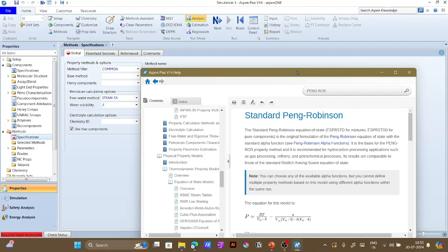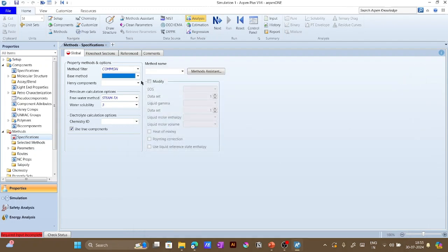In that also, first you have to find whether the property estimated by Peng-Robinson and SRK for your compound deviates too much. If yes, then this property estimation method will affect your simulation result. If no, if that error between the two methods is, let's say, 1 or 2%, then depending upon your system it might be important or it might be very irrelevant. So this way you have to decide and eliminate various methods, right?